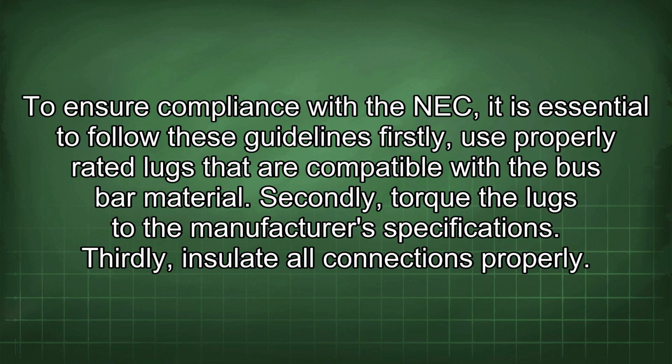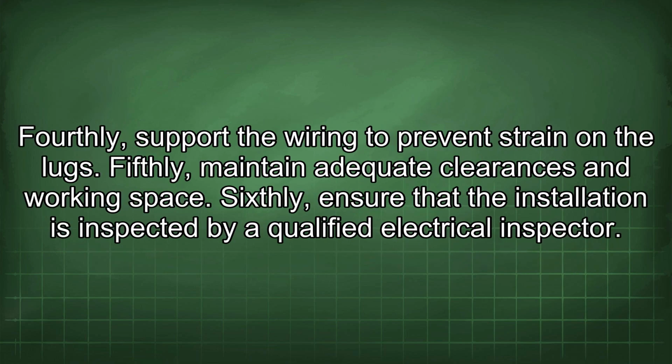Firstly, use properly rated lugs that are compatible with the bus bar material. Secondly, torque the lugs to the manufacturer's specifications. Thirdly, insulate all connections properly. Fourthly, support the wiring to prevent strain on the lugs. Fifthly, maintain adequate clearances and working space. Sixthly, ensure that the installation is inspected by a qualified electrical inspector.